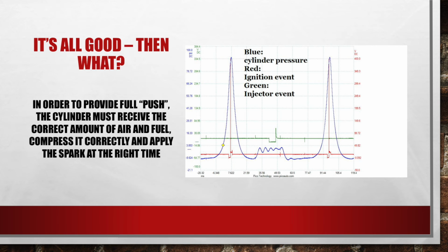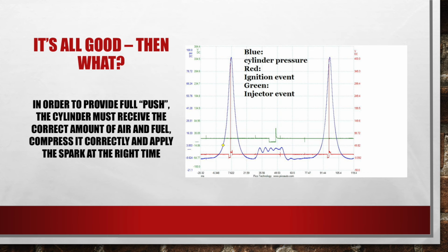If you've gone through the basics, and again, especially with single-cylinder misfires, and you've verified that everything related to the fuel system is okay, everything related to the ignition system is okay, and the cylinder is mechanically sound, there's no problem there, don't forget that all of these events have to occur in the right amount and at the right time. And one of the neatest ways to check that now is using an in-cylinder pressure transducer to look at the mechanical condition of the engine.